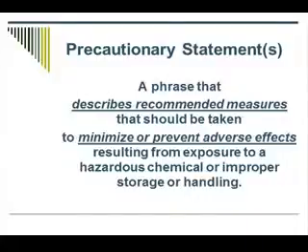You will also see a precautionary statement. These are phrases that describe recommended measures that should be taken to minimize or prevent adverse effects resulting from the exposure to a hazardous chemical or improper storage or handling. Some examples of precautionary statements are: store separately from flammables and combustibles. Keep containers closed when not in use.